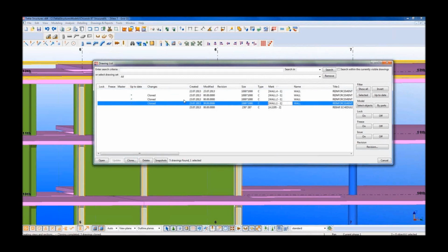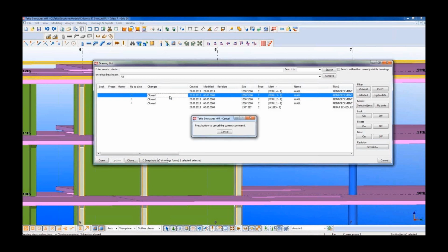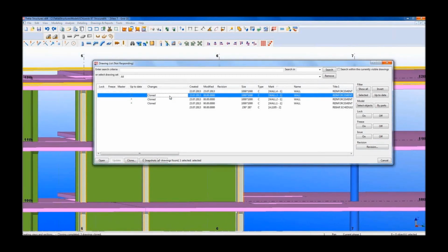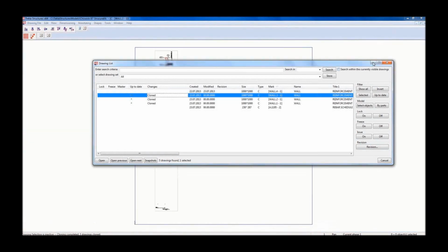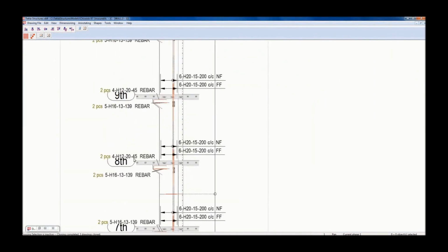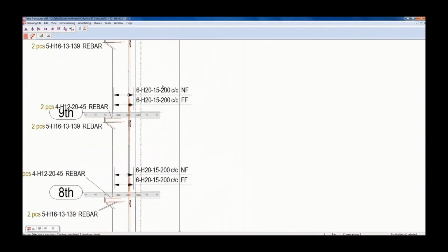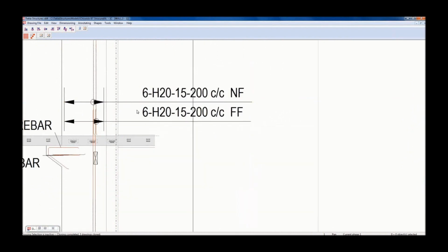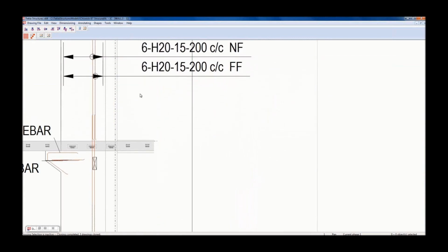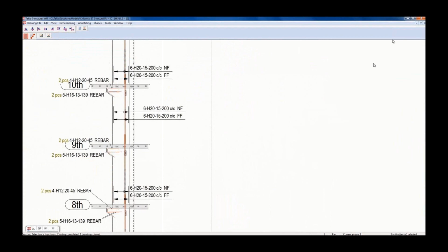I'm going to concentrate on the RC drawings though. So basically you get a sheet of every window, of every wall. If we just open one of these clone drawings, even though the walls are a little bit different, they do actually clone quite well, and you also get extra notes on for the bars that aren't going to be ranges or might not be ranges. So you just come in and there's a little bit of tidying up to do. You can drag stuff, change stuff, pull stuff, just to get the drawing a bit more presentable, if you like.